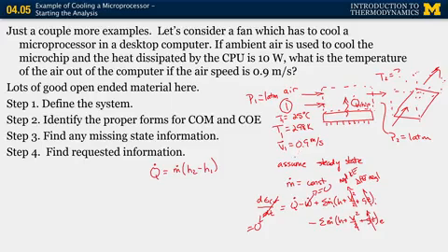You know it's not in the saturation region because it's air at ambient conditions. So pressure and temperature are enough to fully define the state. At the exit condition, you're trying to find temperature, and you have an assumption about the pressure, which is a pretty good assumption. Okay, so that's not enough to fully define the exit state. So we go back and look over here and say, but I have the heat transfer rate, so I can use the heat transfer rate to find the enthalpy at the exit.